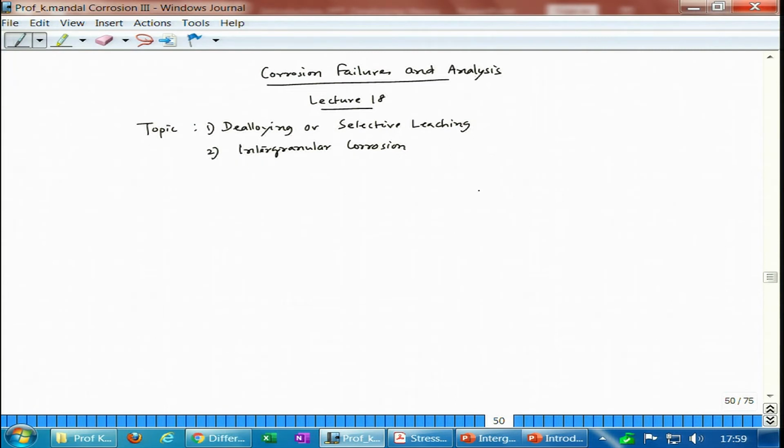Okay. So, now let me talk about graphitization. Okay. So, this is an example, or we call it graphitic corrosion. So, this happens in cast iron. In some books it is written as graphitization. Okay. I think this is my personal opinion, that this should not be used while talking about corrosion of cast iron. Okay. Graphitization means formation of graphite during the cooling stage of a cast iron.